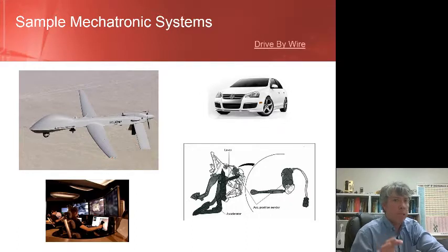Well, we're going to see in a minute all the pieces of a mechatronic system, but this little subsystem in my car actually has the features needed. You see, you need to determine a fairly accurate measure of the throttle position, but what has to be very precise is the amount of fuel that's injected into the engine. And so the injector pump that was built on these cars is actually a very precise device that, unfortunately, costs quite a bit of money to rebuild anytime it's worn out.